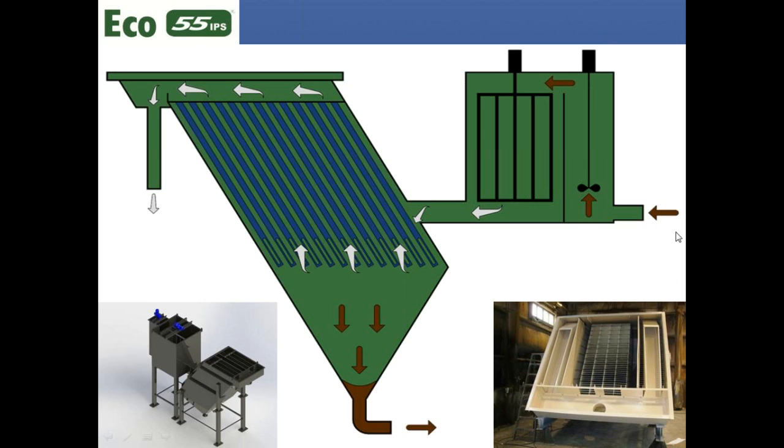That clarification stage will typically begin with a flash mixing stage, which you see in this process flow going from the right to the left. In the flash mixing stage you're doing your chemical injection, your pH adjustments, any flocculant addition. You're doing a maturation process to form a large particle size that will easily settle and separate out from the processed water. And that enters a high rate clarifier.